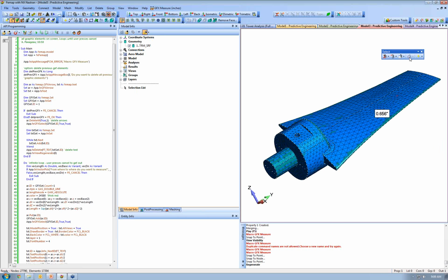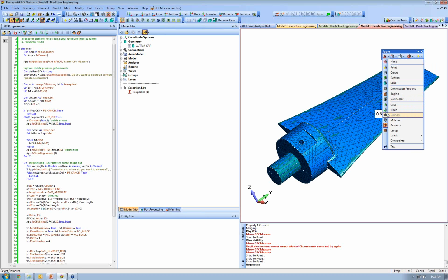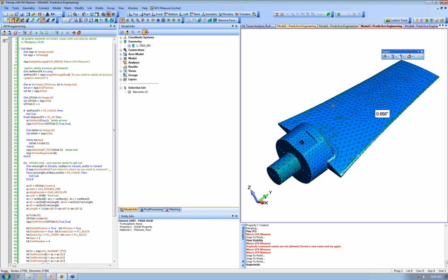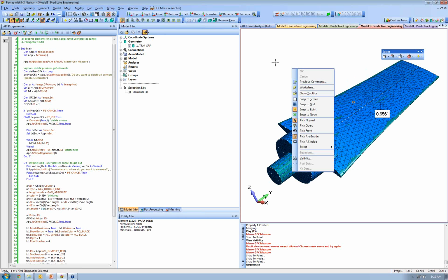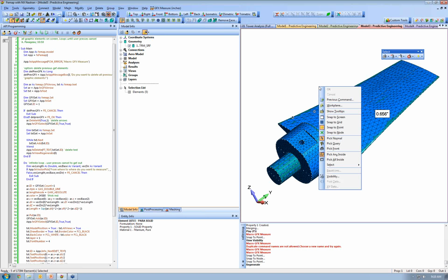This is one of the things on the selector. When you're in selector mode, the standard left mouse button classically means I'm going to select something. But in selector mode, the left mouse means you're selecting it, but the right click is morphed. It's changed to another option. So the FEMAP developer says, well, that's a right click now, only when you're in selector mode. Then the question is, how the heck do you get back to all your standard right-click options? That's where they said, well, okay, we're going to have you hit the Alt key. And it's in the manual. That's what I'll say.